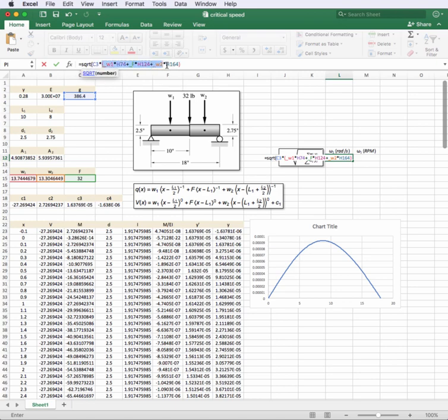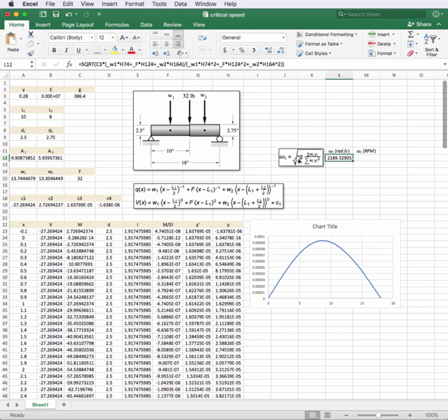And I'm dividing that by, I'm going to copy this and divide by the same thing, and I better close my square root parentheses too, except I actually want to square those guys now. So we're squaring all the deflections, so this is squared and this is squared and this is squared, like that. So I got square root of g times the sum of wi yi divided by wi yi squared, and it looks like it's 2200 radians per second.